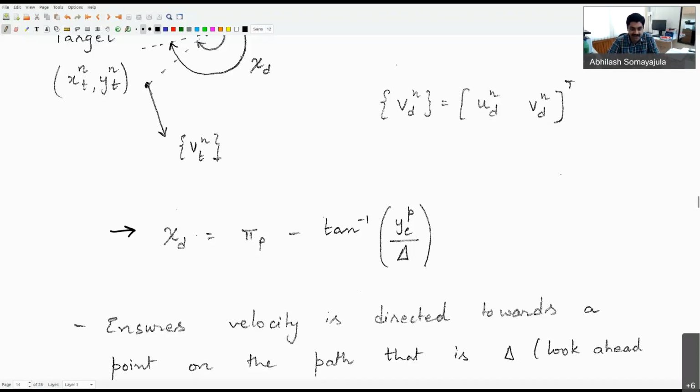So therefore, when we have zero speed applications, this sort of guidance law will not really work. But then it becomes ambiguous also. When you have zero speed, you're not really tracking anything. So it has no meaning anyway, right? So for most purposes, that's fine. But from a measurement point of view, when you are operating at very low speeds, you may be able to get your heading angle precisely from an IMU, but a course angle may not be as precise.